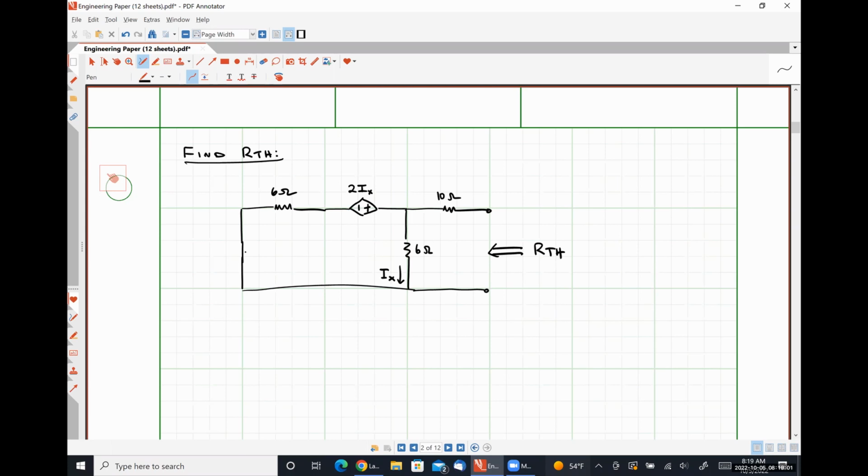We obviously cannot simply ignore it. So we have to find some other relationships to use, okay? So the first relationship that we can use is simply Ohm's law. Our Thevenin resistance RTH will be our Thevenin voltage divided by our Norton current. Always, always, always. Okay. So in this case, that's going to look like 12 volts over 15/17 of an amp.